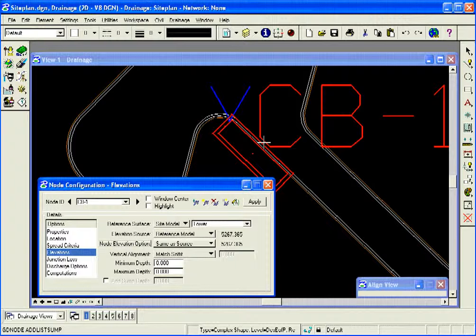That would be a little bit higher than where the actual water will enter the structure. And in that situation, I might set a constant offset of -0.5. So I'll set this back the same as source, because my elevation for the water entering the structure is the same as the elevation it calculated.